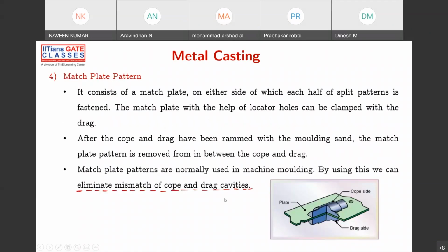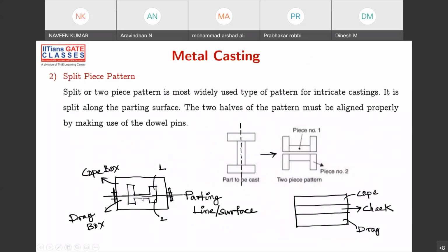Okay, fine. So here, in this diagram, let's say we have put it. Then how are you pouring? You have completely clamped it, no? Where do you want to pour the liquid? So what you do, you add some kind of sprue here, like this. From the sprue, it will happily pass on to all these things, and then to accommodate the liquid and solidification shrinkages, you have to put some kind of riser.